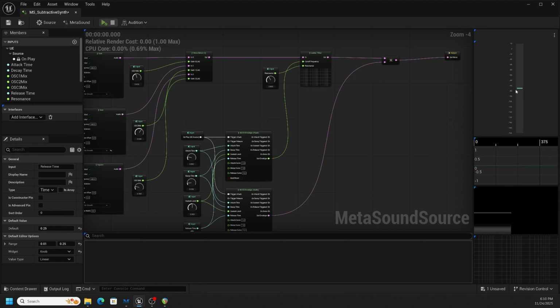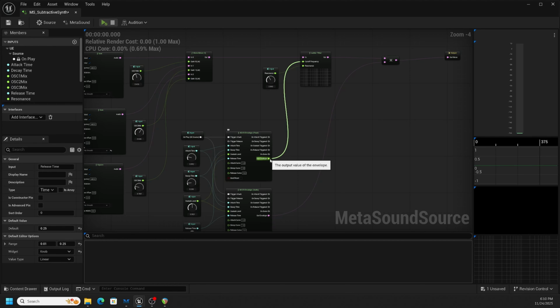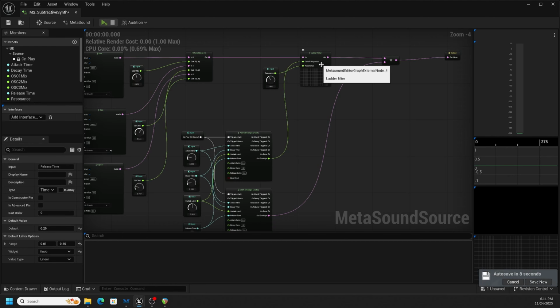It's really low frequency and low amplitude, but the filter is cutting off too much. So here's our first significant problem. We've got a great envelope, we've got a great filter, but we haven't conditioned or scaled the control signal to work with this. In more elaborate or more refined tool sets, you might have a knob here that helped me adjust this gain. We'd have a gain stage for how much this is controlling the filter. We just need to build that in ourselves.